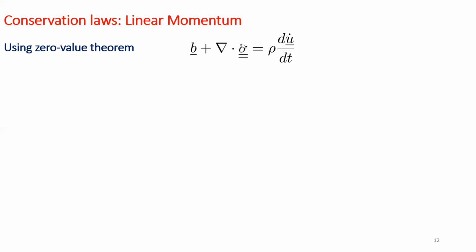And the new term which you have is the term which takes care of the elastic nature of the object. As I said, people call this the force balance equation or equilibrium equation. One can as well call it Newton's second law in elasticity. We are going to deal with static cases in this course, so I'm going to set the derivative with time as 0.